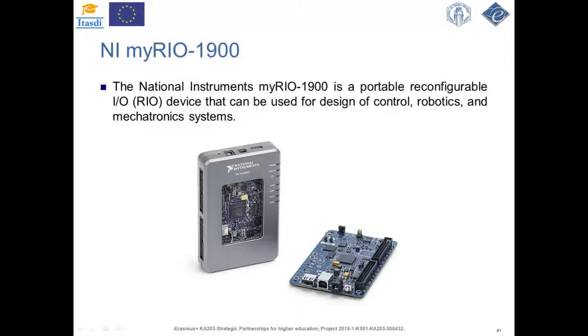The processor will be used for the processing part of the application, the feature extraction method, and for implementing the classification method, while the FPGA will be used for measuring, because it has analog inputs. It will be used for measuring the voltage signal that will be classified somewhere in the power system.